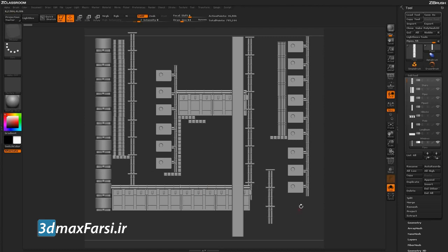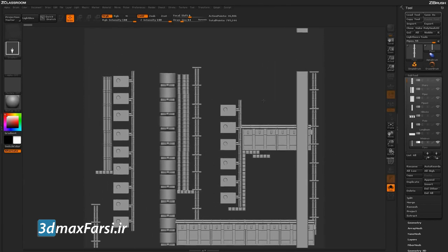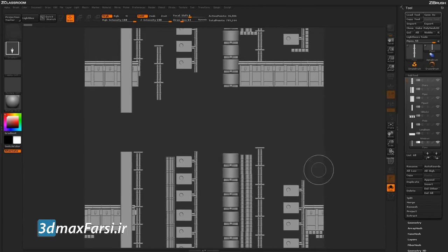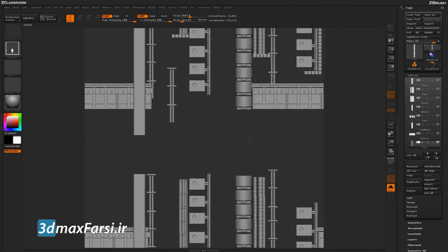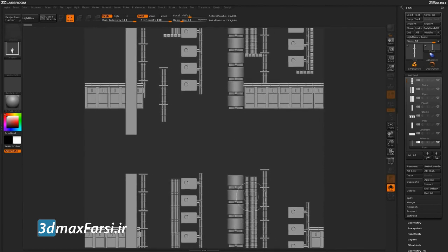Now once I'm out of edit mode, by just coming up here and clicking, I can now actually use the tilde key with this 2.5D to actually move this entire canvas here, and it'll actually tile. So I'm just pressing tilde on my keyboard and then clicking and holding and dragging. As you can see now, I'm actually moving the entire canvas there. So as you can see now, I can manipulate this to another kind of aspect here, and now I can do that same process again.